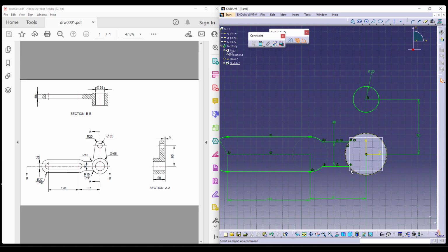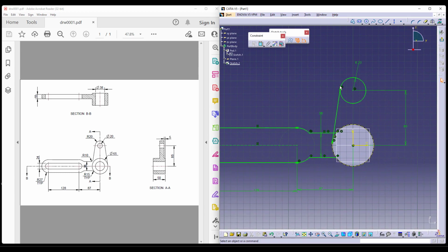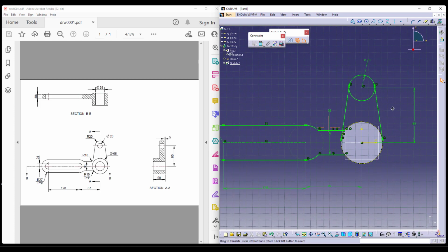Now this is supposed to maintain an angle which is rounds, which can be given a little later. So I'm trying to take a line which passes through this and maintains a certain angle or maintains tangency with this particular circle. It has to maintain tangency here as well. So let's try to do that and say maintain tangency on the top. The same thing has to go on to the other side too. Here let us try what a bitangent line is, and then it works this way.